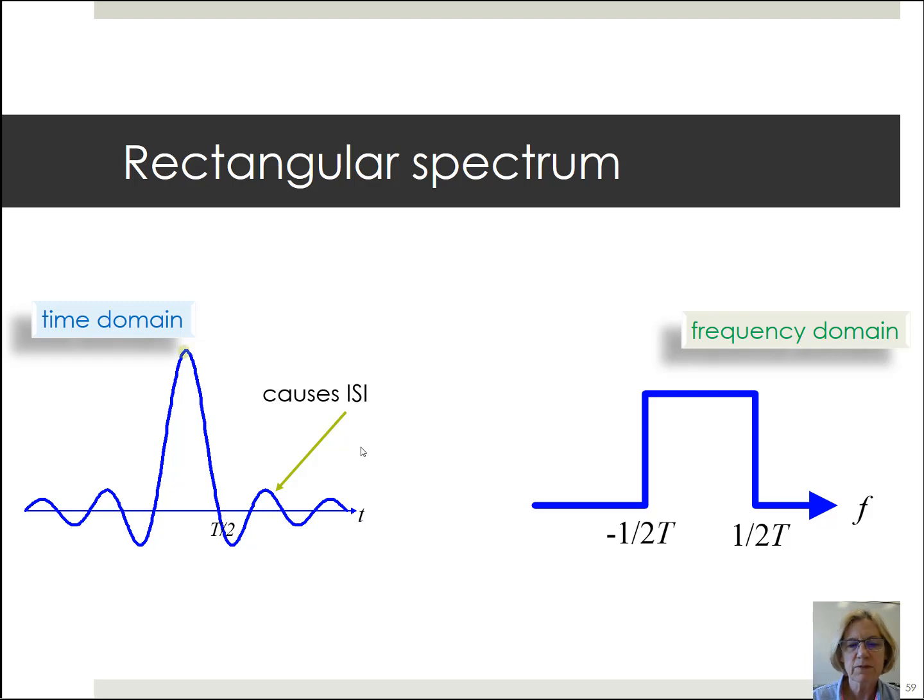Of course, this intersymbol interference should not be too severe, because if we notice, the sinc function does have zeros at the time of the sampling for the next bit. Of course, there are a lot of imperfections in real systems, but at least because it should go through 0, this intersymbol interference should be small. And in the frequency domain, of course, we have this rectangular spectrum, so we no longer have crosstalk. So these are the two extremes.